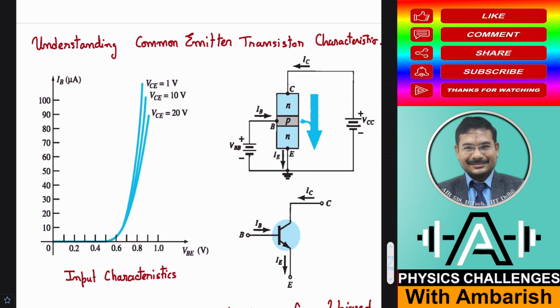If there are too many people to welcome, it doesn't matter. The number of people reaching here will only depend on how many people have crossed. Even if one person has come to receive them, with 1 volt the current is almost the same. And if you welcome them using 10 volts, still the current is almost the same, because more than the number of electrons that have crossed into the collector cannot go here. So there's not much of a difference when you change this VCE. Actually VCE or VCC is the same thing here, because I have not shown any resistance.